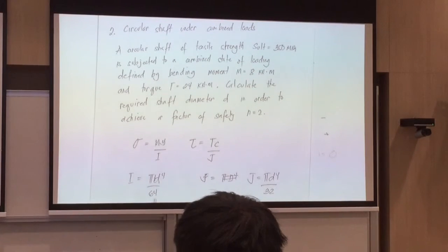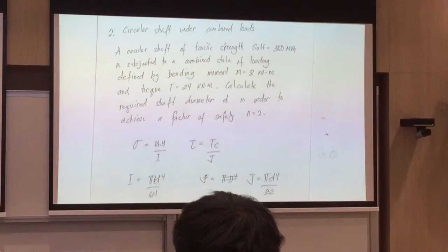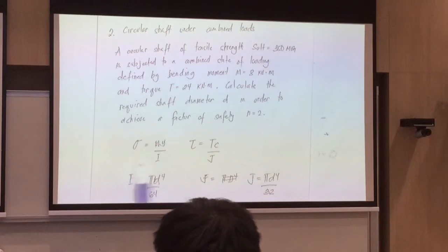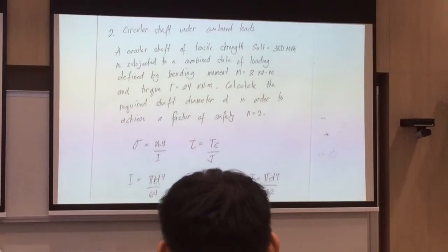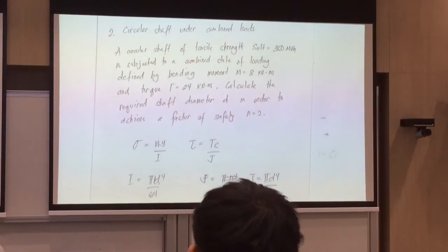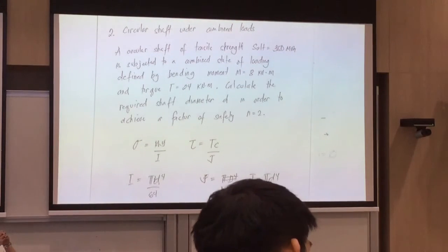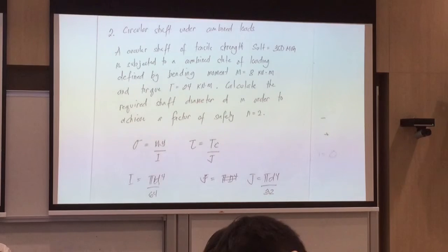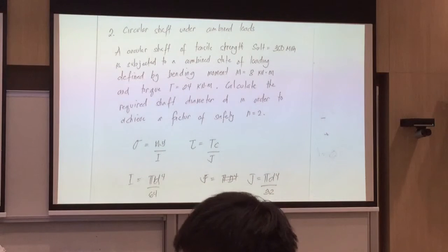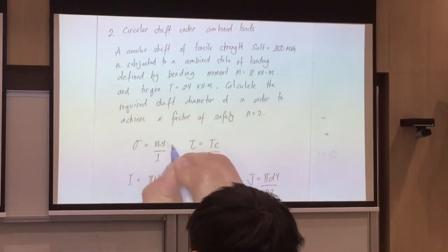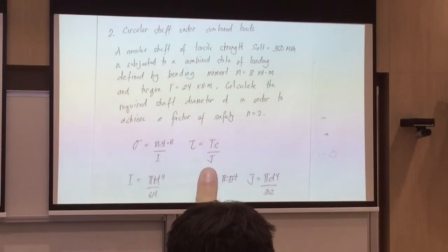By the way, can I ask you, since all of you have a mechanical engineering background, if you have stress equal to My over I, this one is stress due to bending, what will be this y? My over I. If you have a solid circular shaft, what will be that y? Radius. What about torsion?